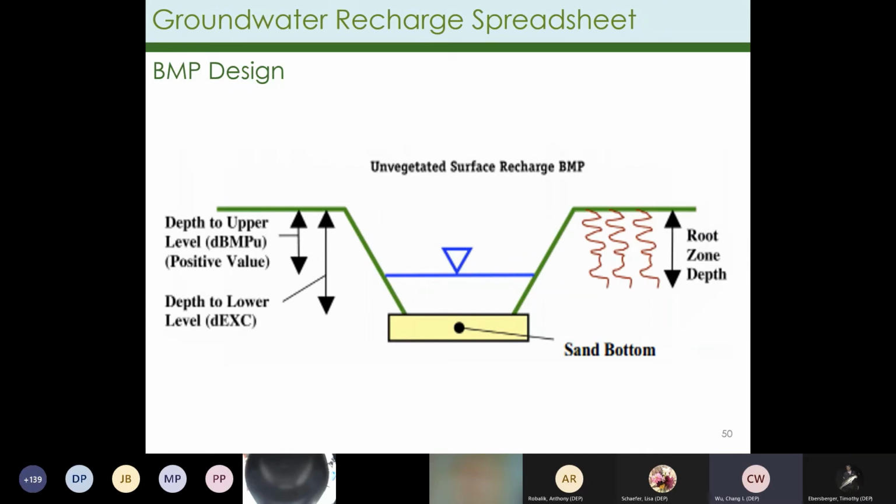And for another case, for example, this is like an infiltration basin. Remember that for an infiltration basin, we said that it cannot have vegetation on the bottom of the basin. So the vegetated ground would be the ground above the basin. It's the surrounding ground level.